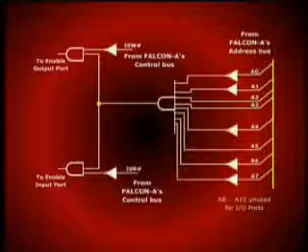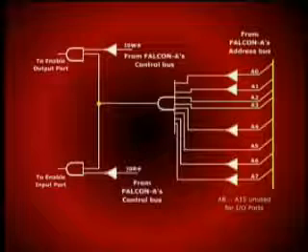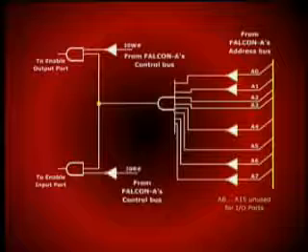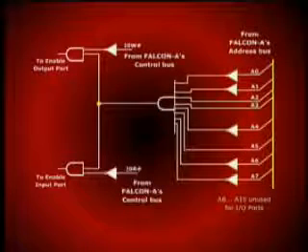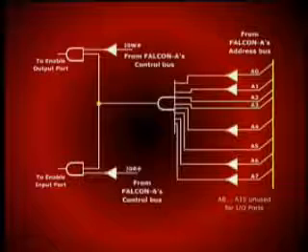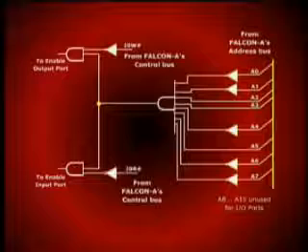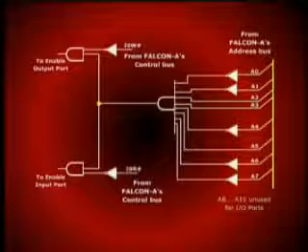Note that now both the control lines I/O read and I/O write are used. This would differentiate which particular register would be written to or which particular tri-state buffers would be enabled. In the diagram, you see the input of the 8-input AND gate has data from A0 up to A7. Some of the lines are inverted, others are non-inverted, which depends on which address we are using.